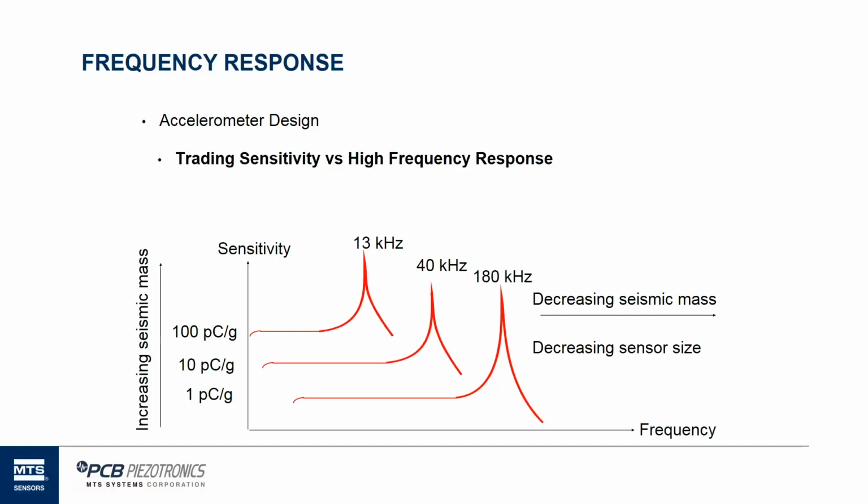So the other thing, not only does the sensitivity change, but as we go higher in frequency, it's a lower sensitivity. It's also a lower mass, because it's literally the difference between a sensor that weighs 5 grams or a sensor that weighs 200 grams possibly, right? And it's a design trade that works out application